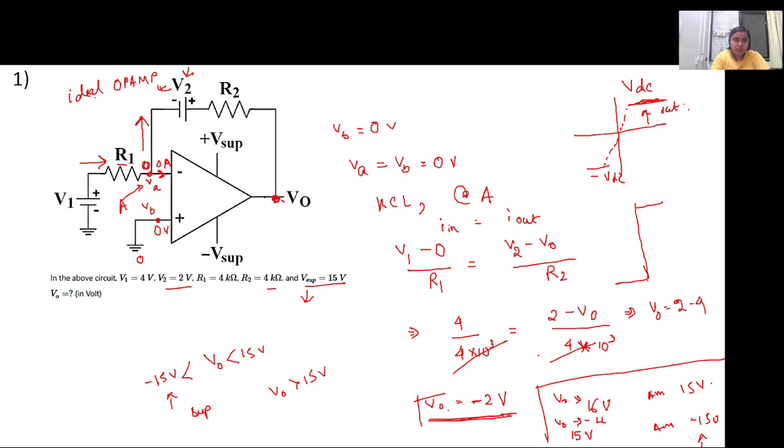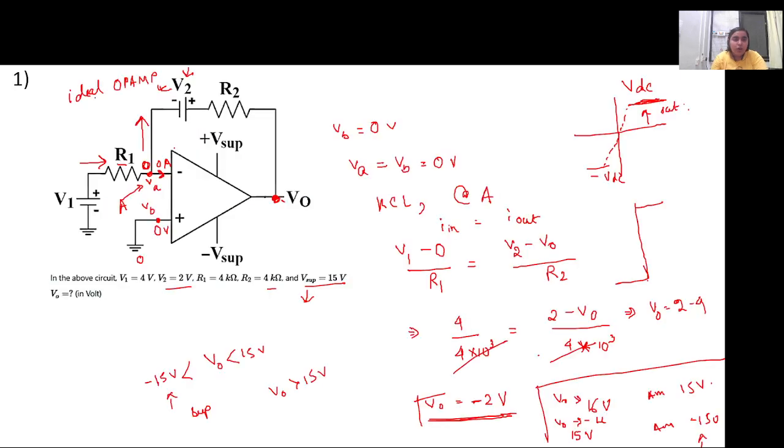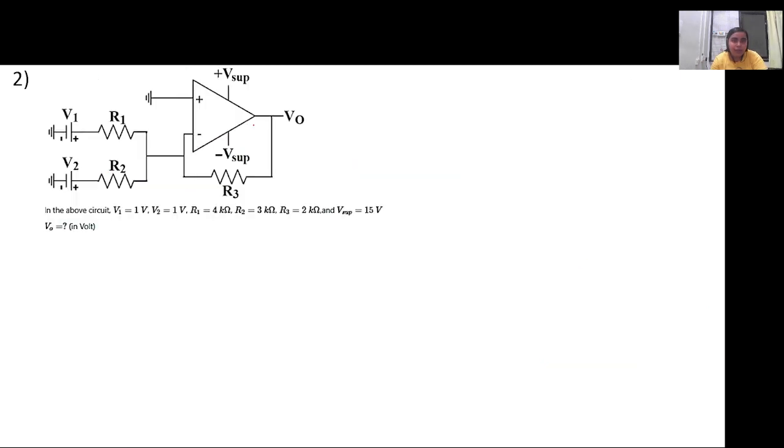No, ma'am. Okay. Then all the questions of the operational amplifier will be pretty much simple, only the circuit will change. One thing to note is that the feedback gain, the closed loop gain given in the circuit, will always be connected to the inverting terminal. In each circuit you will see this. For example, here this feedback loop is connected to the inverting terminal of the circuit. It is always connected in that way.